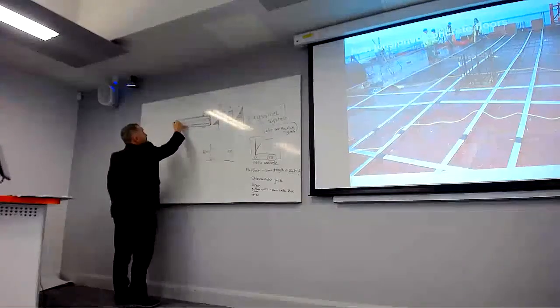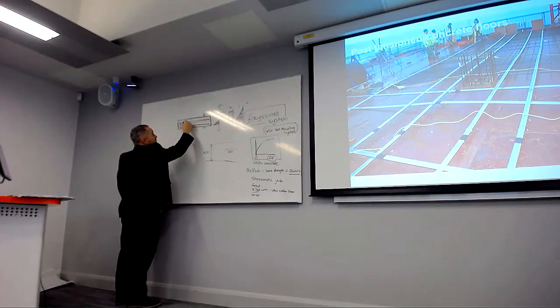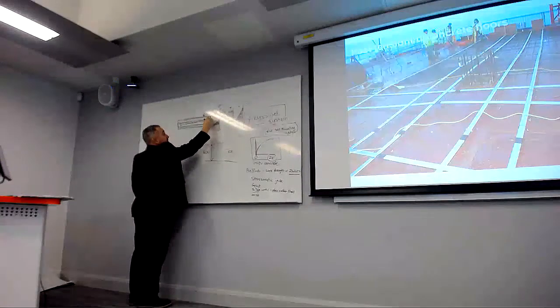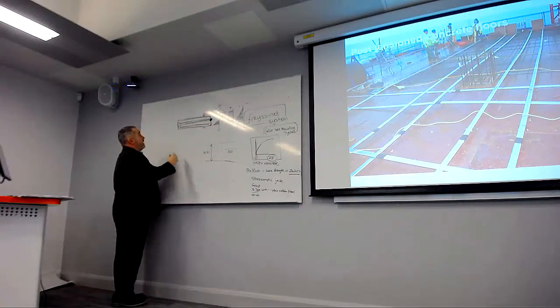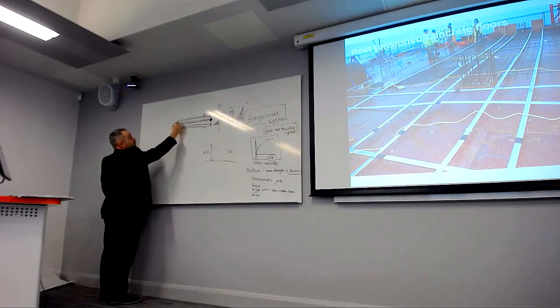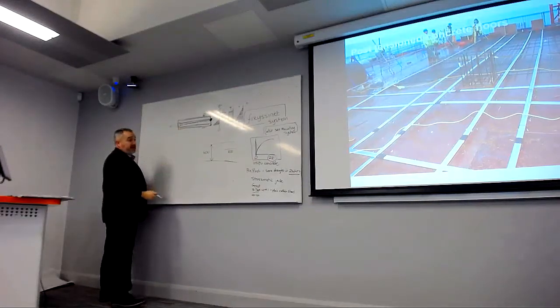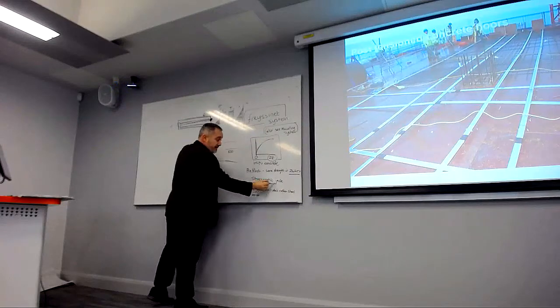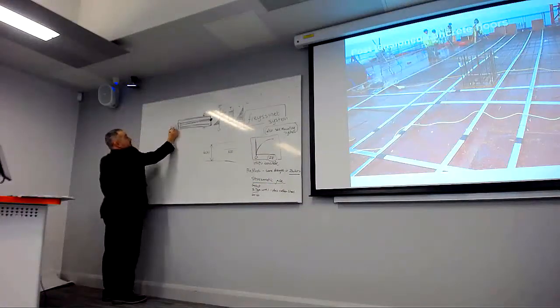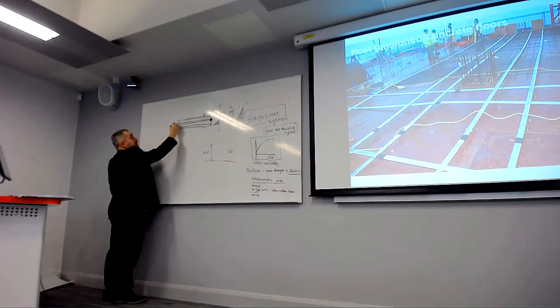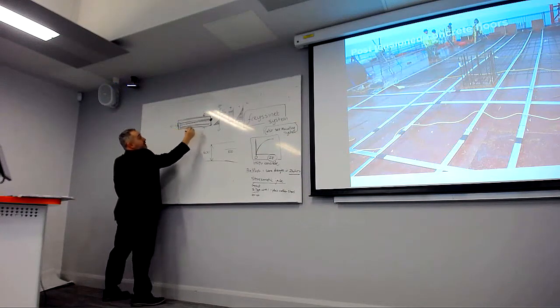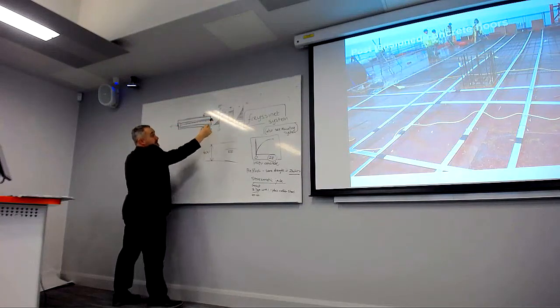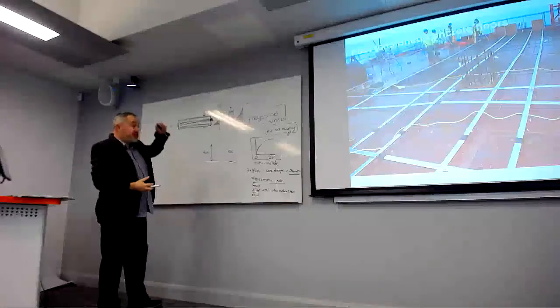There's a sock or a tube going all the way through the concrete, and you attach the steel at one end. Once all the concrete's cast, we pull the steel using a stressomatic jack. When it's pulled to the correct tension, the anchor then squeezes the concrete and creates a tensioned floor.